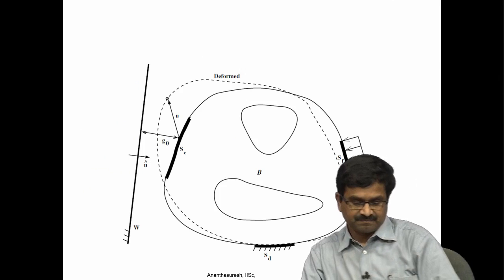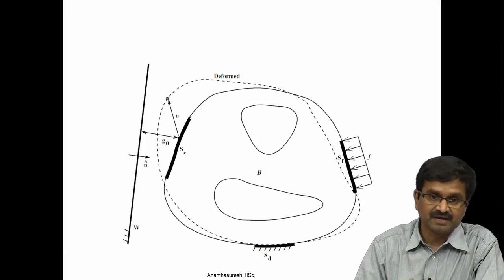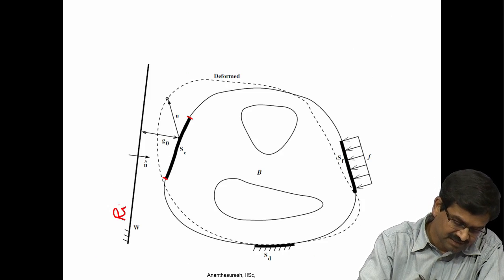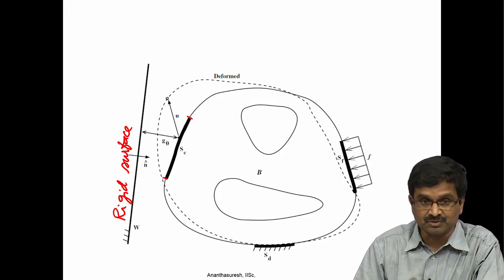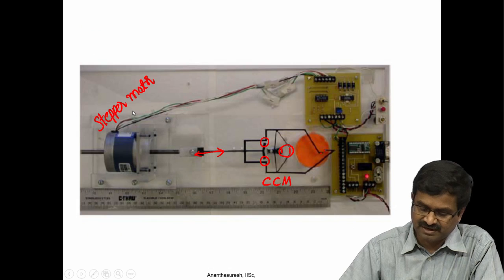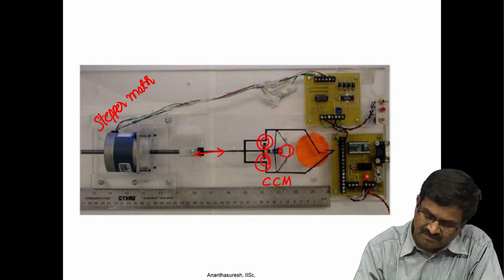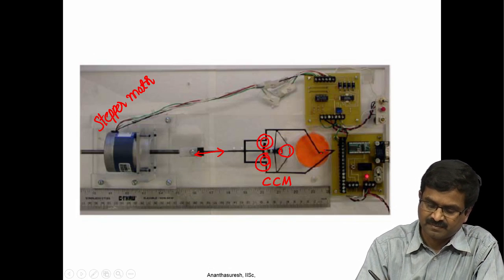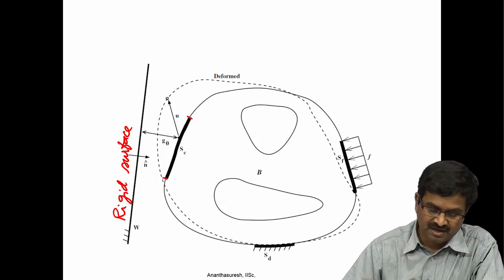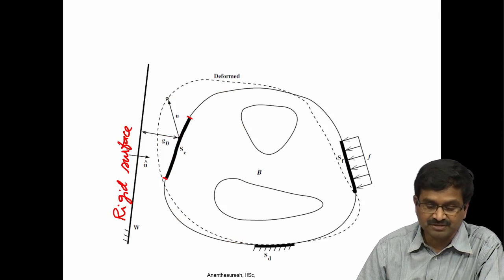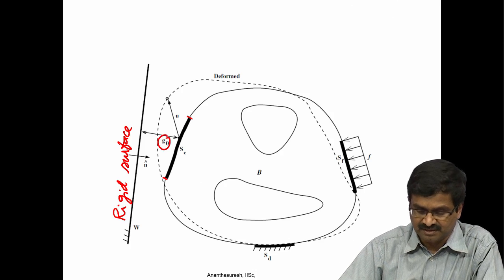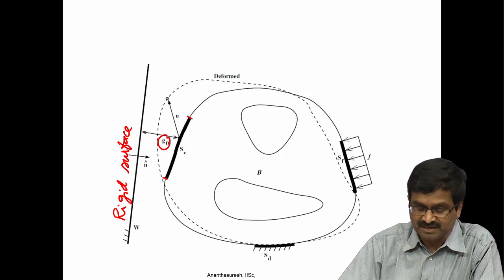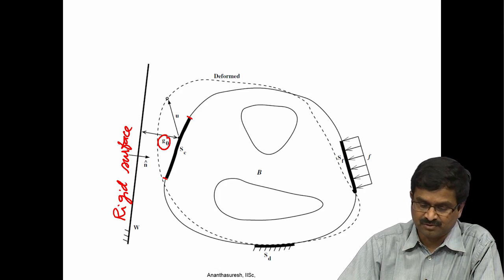So, in general if you want to model it, what we need to do is model the contact between a potential portion of the compliant mechanism, you need to know it ahead of time, and a rigid surface. It can also be a flexible surface and it can be a self contact. A compliant mechanism can touch itself also, like it happened in the second and third contact, actually self contact. So, over here this is self contact, whereas this is touching the rigid surface over there. Okay. So, a self contact can happen or with a rigid surface, and we should model that also by defining either potential function or springs that vary their stiffness based on the gap value. That is a new thing that was introduced here in synthesis that we had discussed earlier. This contact modeling should also be included.